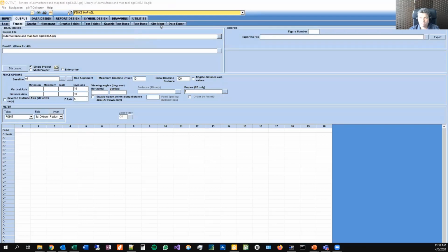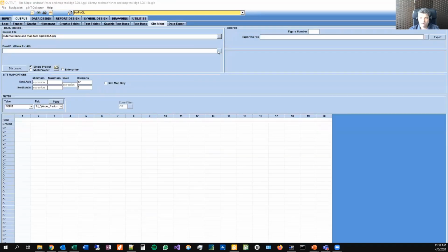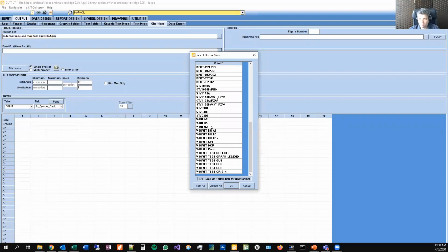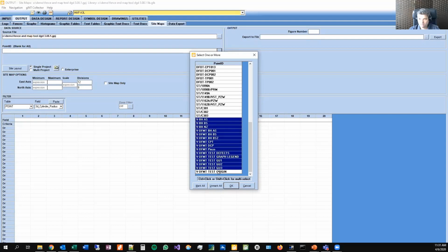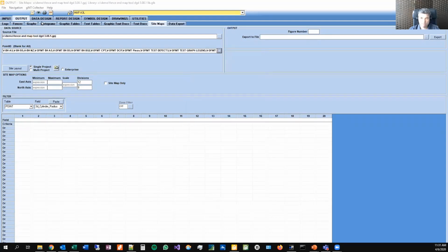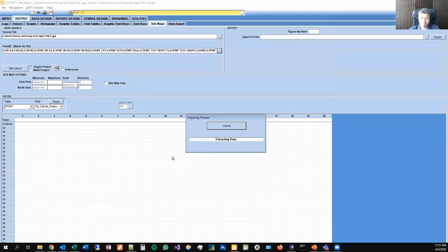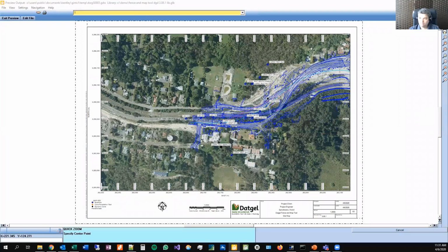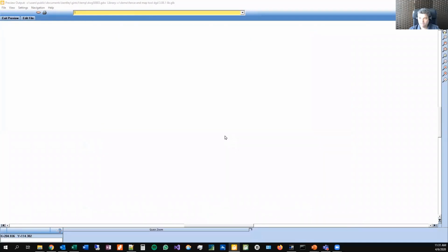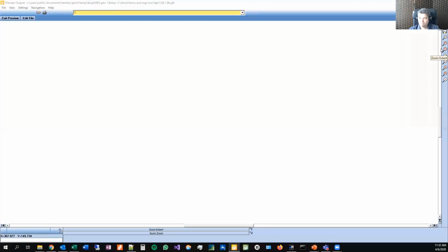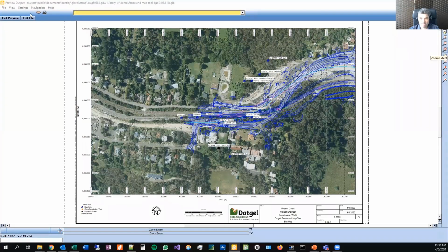So I'm going to jump to the sitemap reports. Choose that one. I'll pick these. Better I do these ones. These reports, these boreholes, preview. Now I don't need to set a scale because it'll best fit the data to the page. All right, so it's done 1 to 2000. It picked that was the best next good scale in my list. So these are the boreholes. It's just pretty self-explanatory, isn't it? So we'll exit that.